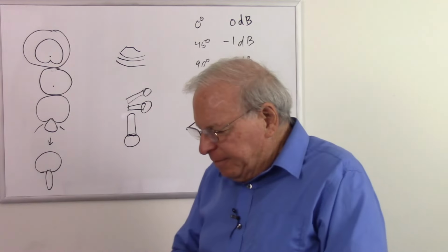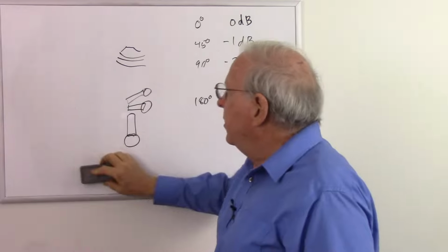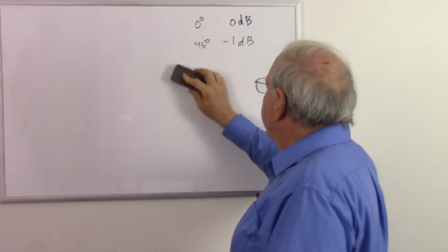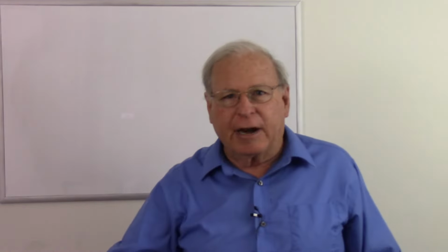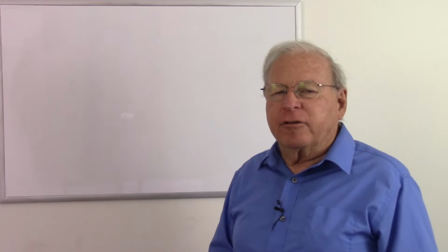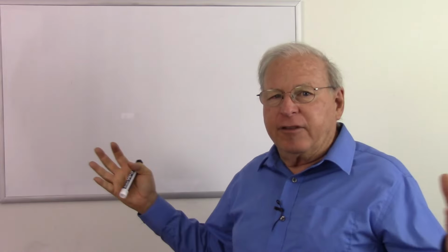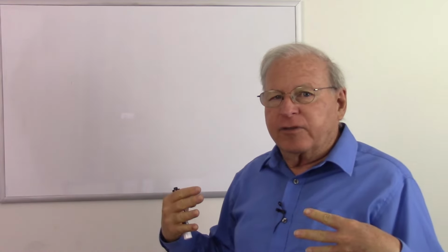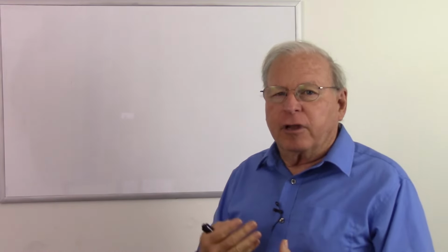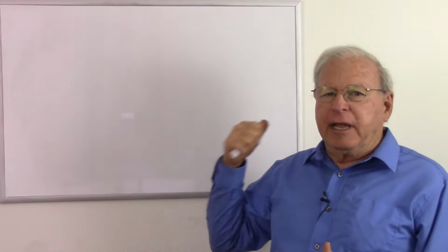But when you go and buy microphones, you're basically going to see two main types. You're going to see the omnidirectional and the cardioid. Those are the most popular types of microphones. But there are some other types. Of course, we talked about the ribbon microphone, which is a bidirectional microphone. So like the cardioid, the bidirectional microphones are good because they pick up sounds from front and back, but not from the sides. So if you want to eliminate those sounds, you have the natural ability of the ribbon microphone to eliminate those sounds, but the cardioid will also eliminate sounds from the back.